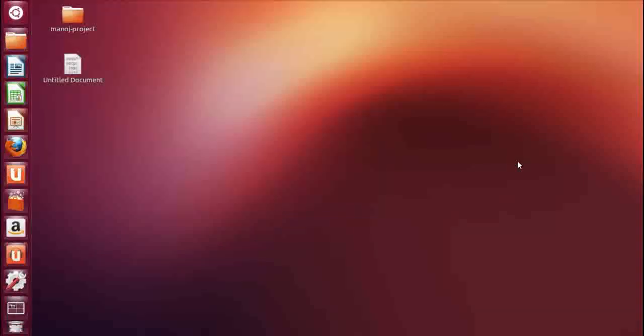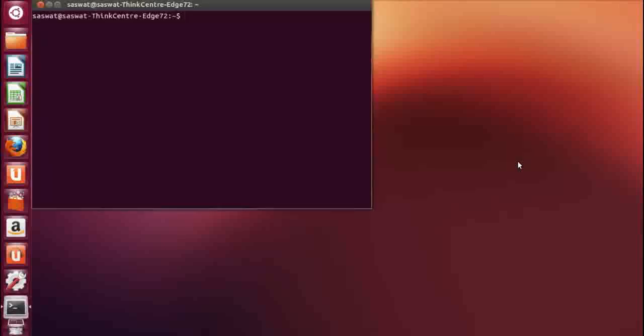So we have learned how to draw the layout by using the commands in the TKCon window like paint, N-diffusion, P-diffusion, etc. Now we'll learn how to draw the layout by using the toolbars present in the magic tool. So the same procedure, I will open the terminal window by pressing Ctrl Alt and T. Then we will type magic -T scmos.